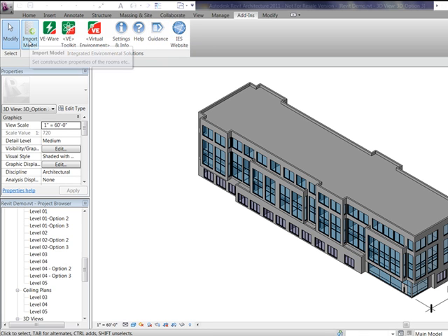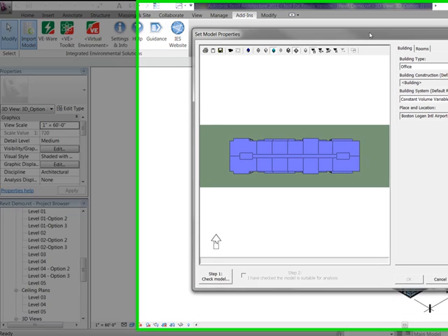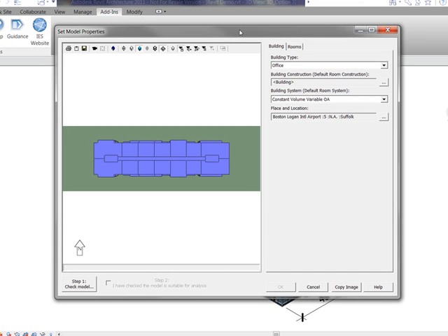So then to bring our geometry in, we're just going to go into the Import Model button and hit this. And it's going to start running and finding all of the rooms and spaces inside of my project. So for Revit MEP, these are going to be spaces. For Revit architecture, we're going to be bringing in our rooms. And it's important to have things like our room and area settings turned on. We also want to make sure that we have the rooms set, again, to find volume, but also set to fill the entire room.